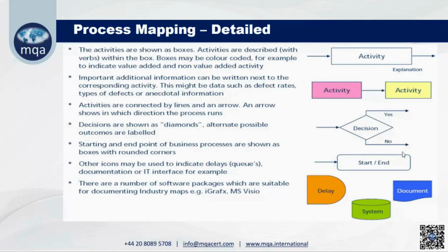It is the same. Then in some places there will be delay. This delay is basically due to cycle time. Sometimes in a process we are not balancing the process. Like one process is taking 1 hour and another process is taking 45 minutes, so there will be a 15 minute gap and a delay for the next process. So we will use the D symbol. We will use an arrow for the direction of the process.